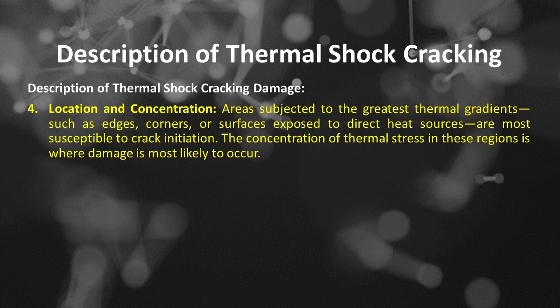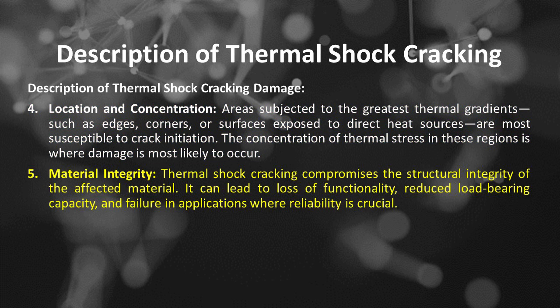Number 4 is from location and concentration of thermal shock point of view. Areas subjected to the greatest thermal gradients, such as edges, corners, or surfaces exposed to direct heat sources, are most susceptible to crack initiation. The concentration of thermal stress in these regions is where damage is most likely to occur. Number 5 is from material integrity of thermal shock point of view. Thermal shock cracking compromises the structural integrity of the affected material. It can lead to loss of functionality, reduced load-bearing capacity, and failure in applications where reliability is crucial.